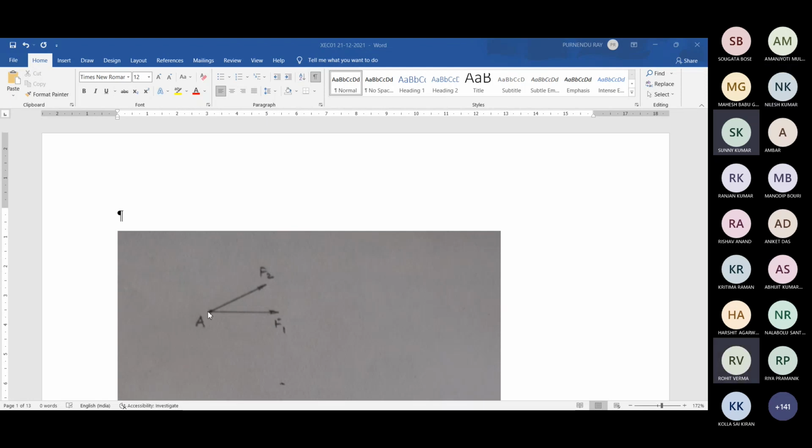Now suppose on the other side of the ring, you tie one very fine inextensible string and try to pull it and bring that ring back to its original symmetric position, whose center will be matching or overlapping with this pin. To bring it back to its original position, you need the force to be applied in a particular direction: opposite to the resultant of F1 and F2.